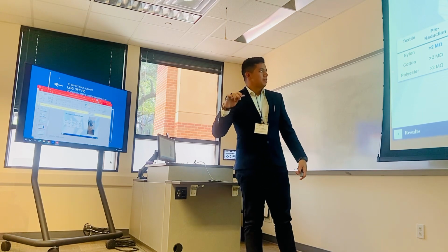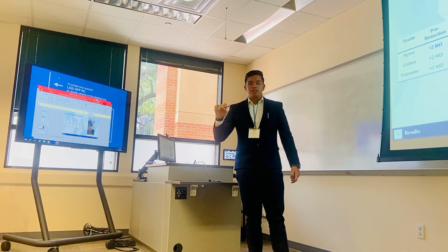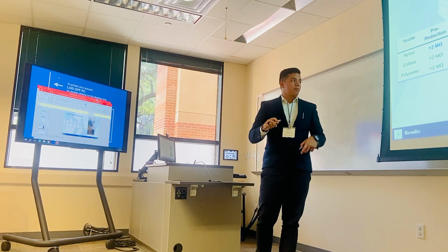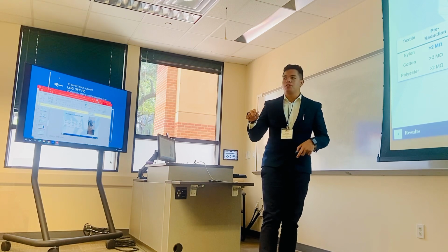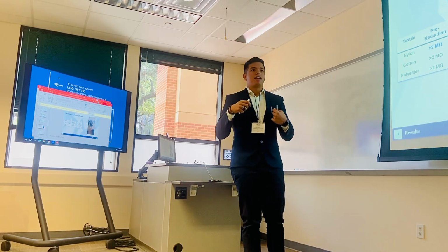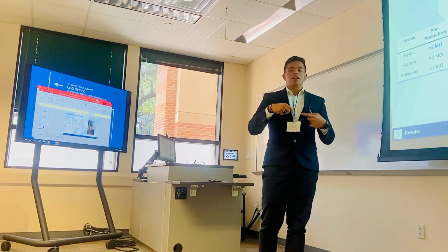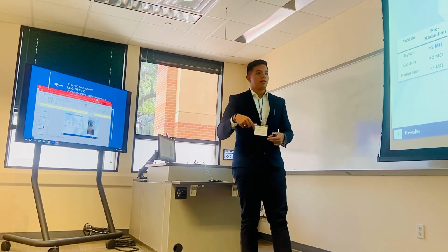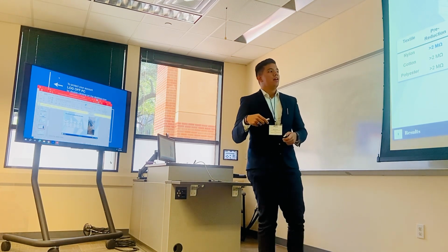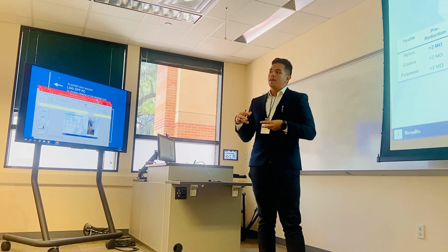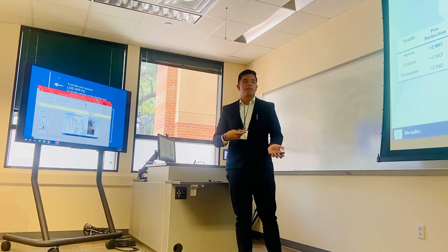So when we started with the pre-reduction, this is just with the graphene oxide deposited, the resistance was quite high, like above 2 mega ohms for all textiles. And this is the same value because the actual ohm meter would not register any more than that. So it is definitely above those values, but once we added it to the reducing solution, it dropped 3 orders of magnitude into kilo ohms. So it's not ohms, but it's still a considerable addition of electrical properties to the device.